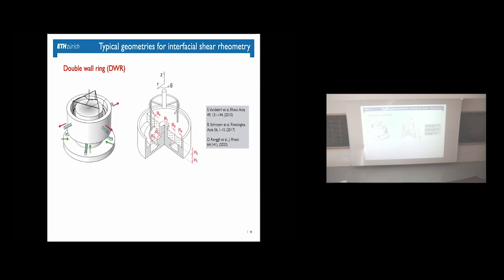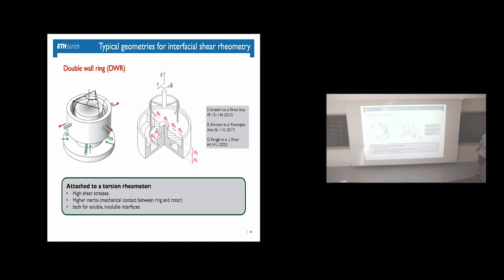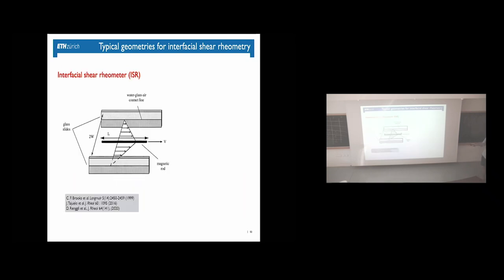There is, however, a bit of an issue. If I have this rod, for example, at the interface, a rheometer has to have clean kinematics, right? We have cone plate to have a homogeneous shear rate in the sample. Here, when I move the needle, I don't decide where the momentum goes, right? The momentum can go at the interface, but it can also go down into the bulk still.